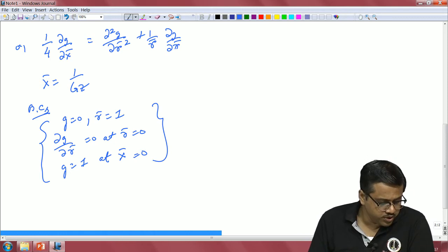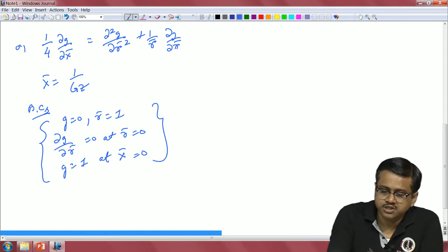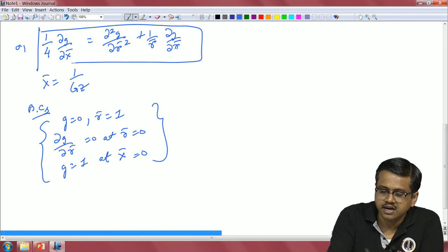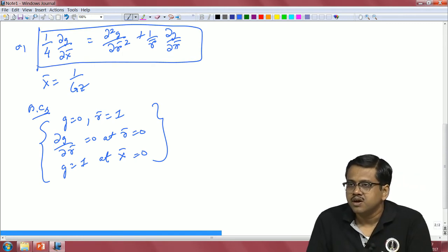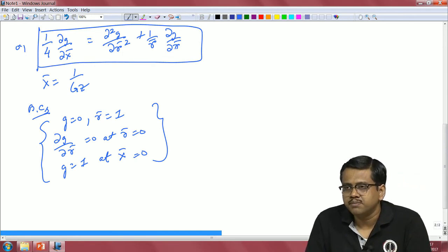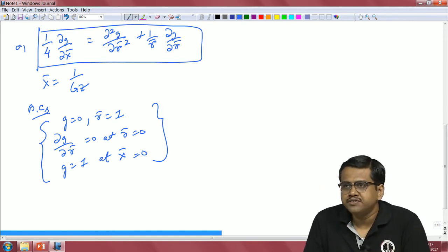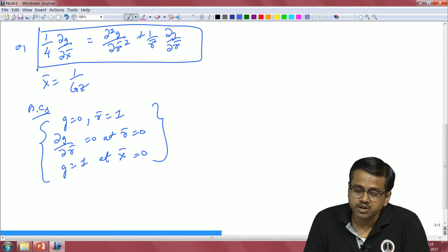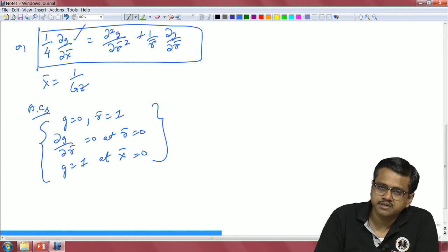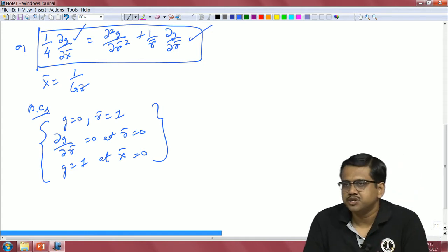Once again, as I told you earlier, this equation that you have represents the unsteady heat conduction equation, where x bar basically doubles up as the time scale. So, normally in a transient heat conduction equation, or 1D transient heat conduction equation, in cylindrical coordinates, this term will be your time, and this will be the corresponding spatial coordinates.